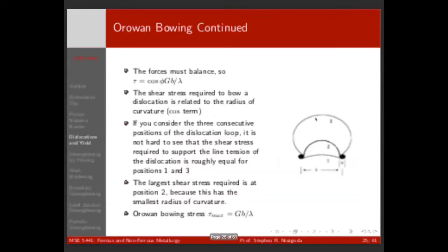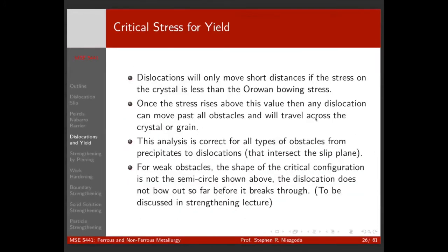So we can create dislocation loops. There's a whole bunch of different sources. People play with single-arm sources, but the Frank-Read is sort of the archetype way of doing this. You can also have sources where you have one pinned segment and the other end hits the end of the grain and swings around like a pinwheel. People have come up with all kinds of crazy theoretical ways for dislocation loops to be generated. But just thinking about the Frank-Read source gets us 90% of the way there.